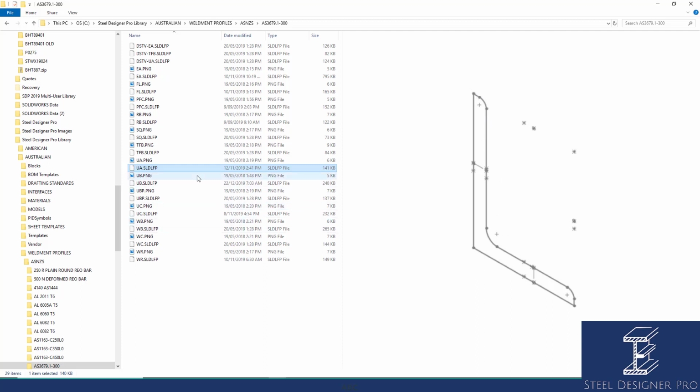So what happens is in the process of creating the section for the DSTV, it temporarily swaps out the angle weldment profile for a DSTV weldment profile, and you'll see the radiuses disappear. So when it takes a section cut, it cuts it down the inside sketch segment that you see there and forms a plate, and it'll do the same thing on that edge. It'll cut it across there and form a plate.